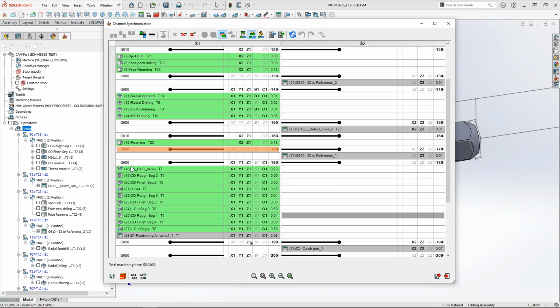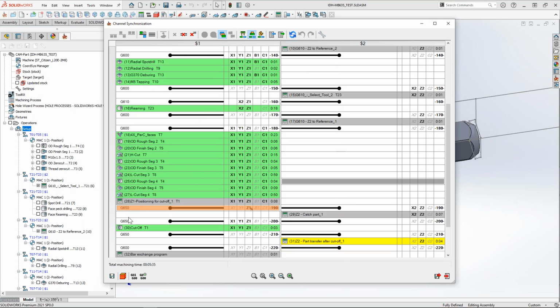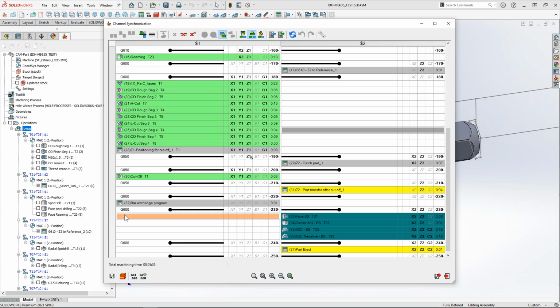For most of the machines that support axis patterns, this is a critical point, because you can actually see it. If you maybe miss something, you will have to change it. In most cases, SolidCAM does everything automatically, but there are machines where you can have more than one axis pattern solution, and for those cases, it is very important that you can actually see this label over here.